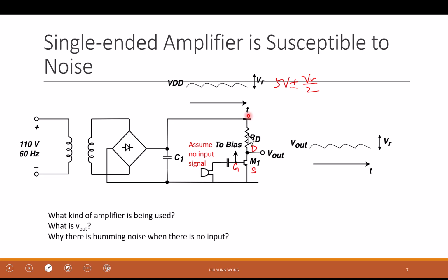And we just have the VDD biasing the V out and go to the output. So it's a common source amplifier. What is this for? I have a microphone here, not speaker, microphone. And it goes into here. And remember, we do need to bias the gates. Here we did not show it, right? We can put 2 resistors so that it is maybe 3 volts.